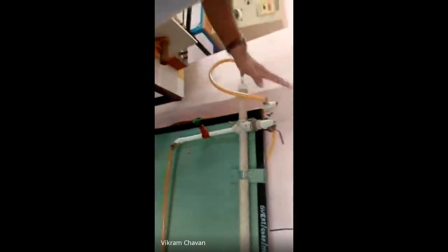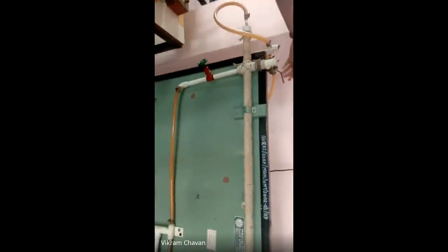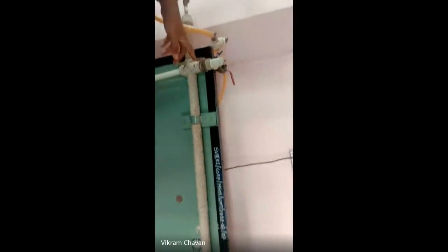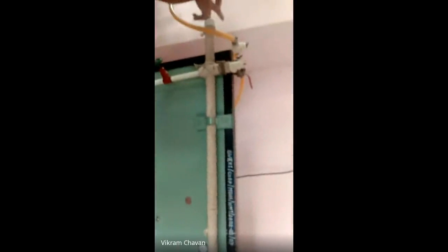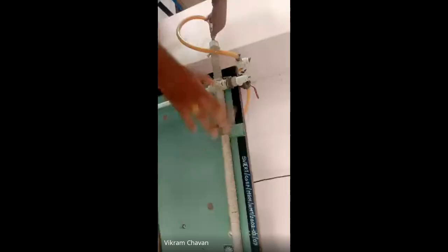Okay, and second arrangement is for the cold water, and this knob is open, so water will flow in this direction, and this knob is closed, so the exit of water from this side will be closed over here. So the water will travel in this direction, and we can say that the cold water and hot water direction will be same, and that will be the parallel flow arrangement. This type of arrangement is called a tube and tube heat exchanger.